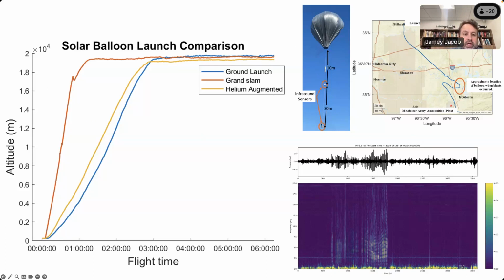Now, one of the things you'll notice on here is you do see our solar balloon has a couple different sensors separated. So we have two sensors on the balloon. Why? It is so that as that sound wave, which is traveling obviously at the speed of sound, hits the balloon, we'll have a short time lag separated by enough distance that based upon our sampling rate, we can determine the time difference between those two, and help use that for range and bearing on the actual source itself.